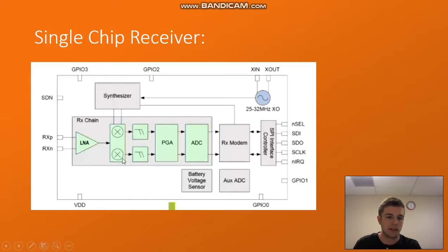Then it goes into the mixer here, which moves it into a low pass filter for the downward conversion after the multiplication of the signals, which can be seen here by the X. And then it goes into the low pass filter and then the programmable gain amplifier, which takes, say, a loud person's voice and lowers its gain so it's not too much to handle, and a quiet signal so it maintains that gain of whatever we want. And from this, it all has good swing, and it goes into the analog to digital converter to get it into a digital signal, similar to what we saw before.